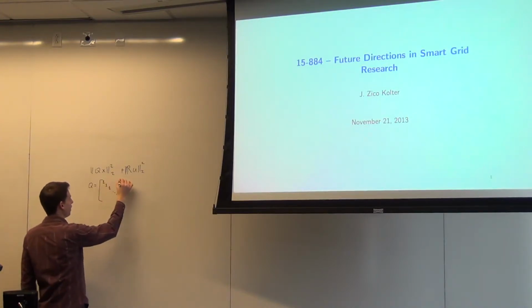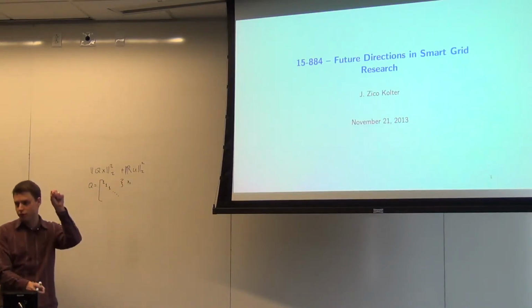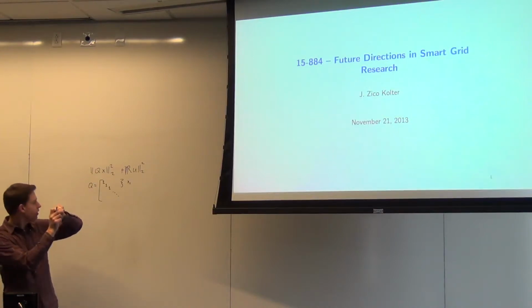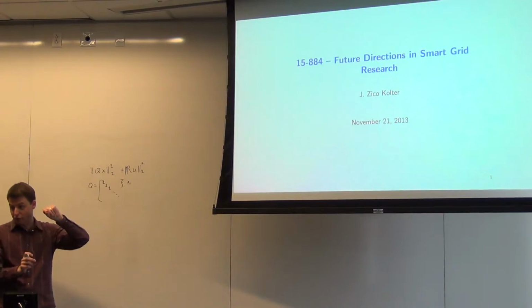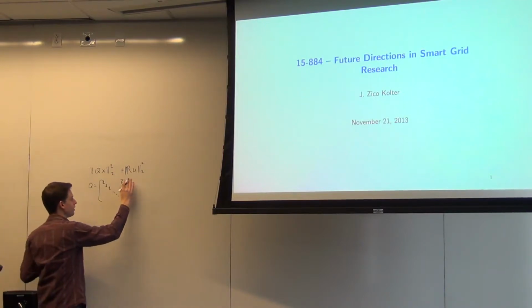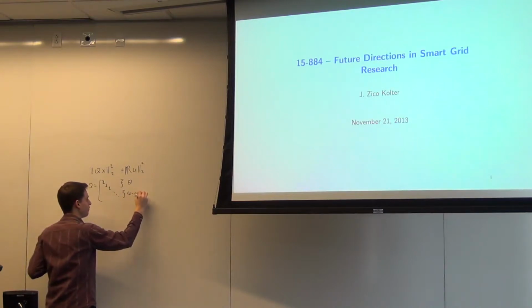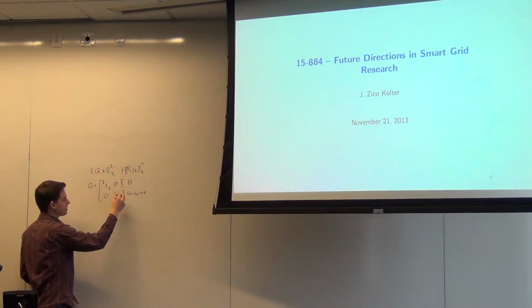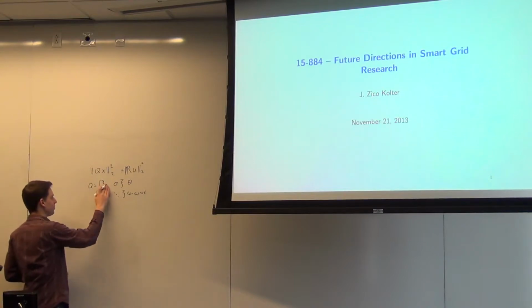And this block here is going to be for all of our theta variables, and then the next block is going to be for all our omega minus omega ref variables. So this is the theta block here, and this is the omega minus omega ref block here. And so you just choose it to be diagonal, and essentially if you're not tracking your theta well enough, then you say, well, this isn't high enough, so I'm just going to bump this up to, say, 2 here.